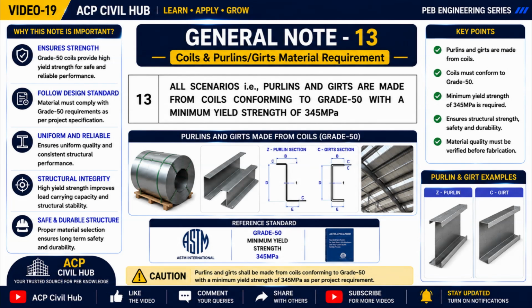Since purlins support the roof sheets and girts support the wall cladding, selecting the correct material grade is essential for maintaining the building's structural performance under wind, dead, and live loads. During fabrication, engineers should verify that the supplied steel coils meet the grade 50 specification and that the manufacturer's material test certificates confirm the required mechanical properties.